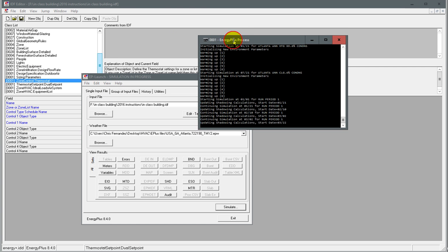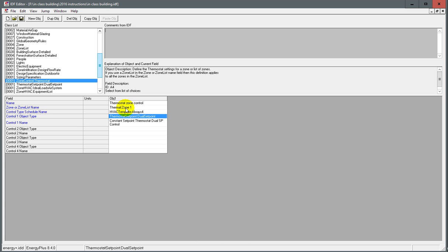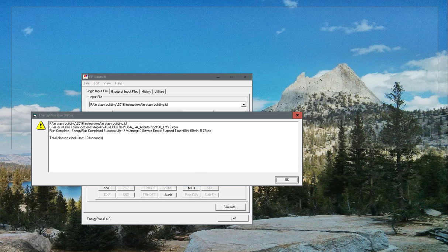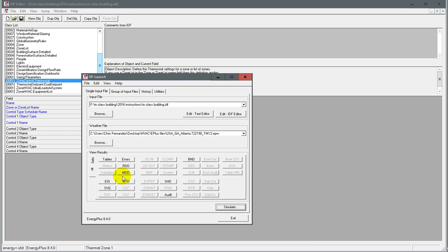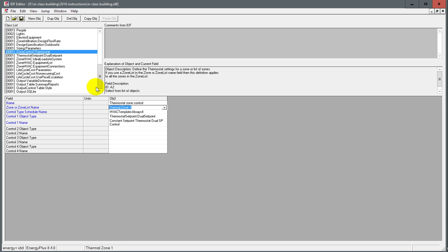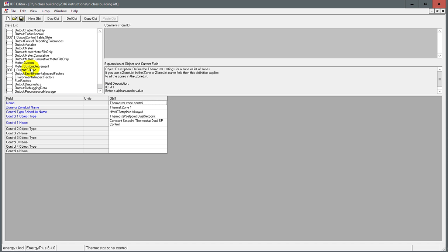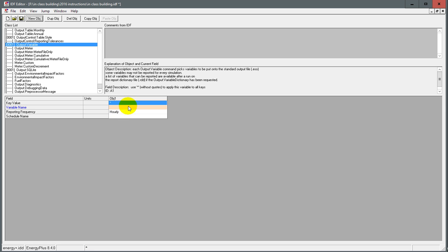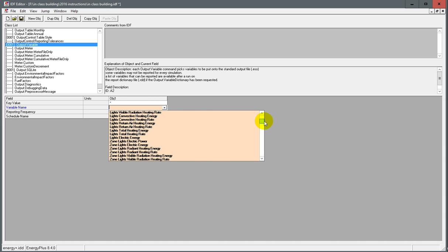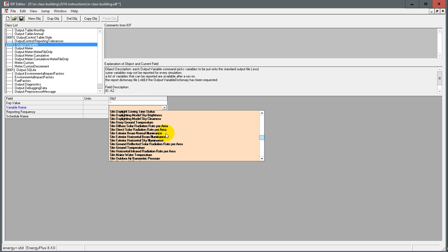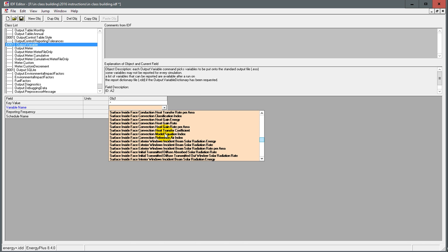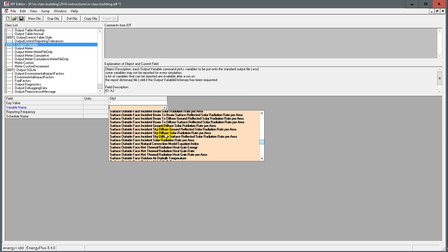and also this is just for it to work, because I don't have the other zones here. Yours should be all zones here. And so here we go, 0 severe errors. So now that it's run and it's happy, we're going to go back, Control L to expand it, go back to output variable, new variable, and now everything should be in alphabetical order, or it's not. And we're just going to do the same thing as before, but now there's a lot more options. So there should be a list of whatever you want.